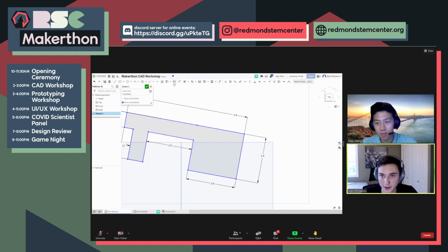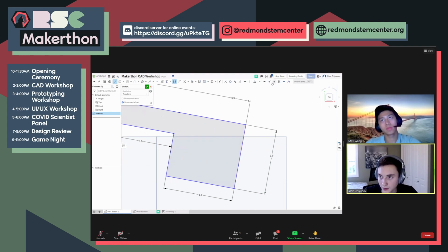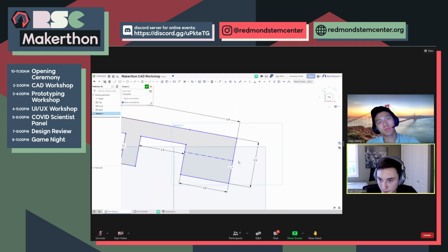So how you get to that is you press construction up here, and you press whatever body. So let's say I want a line, and I want to make some construction lines right here. I'm going to go ahead and let Onshape find me the midpoint there using the autocorrect, or you could also use the midpoint constraint up here. So this is now parallel to that. And now we want another construction line, which I'm just going to get to by pressing construction and line and getting a cross going on here.